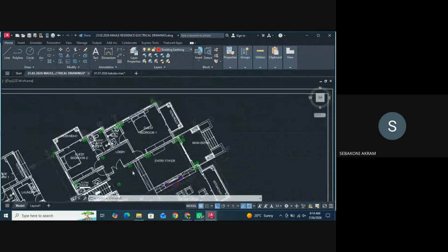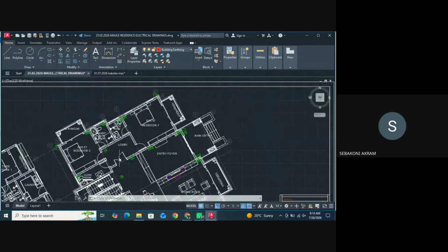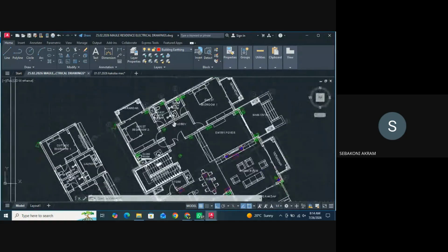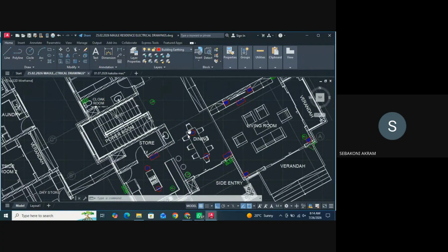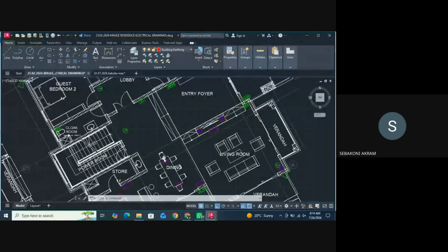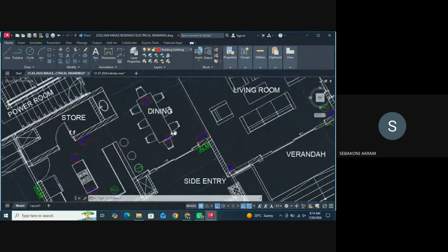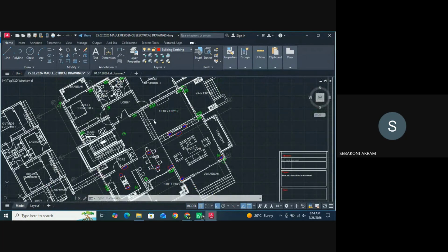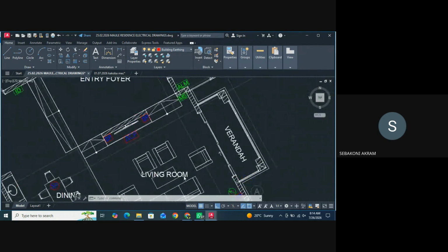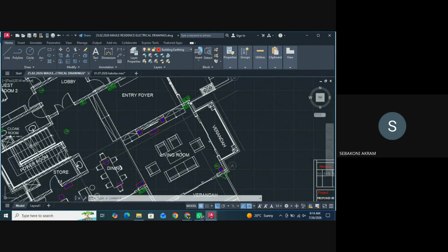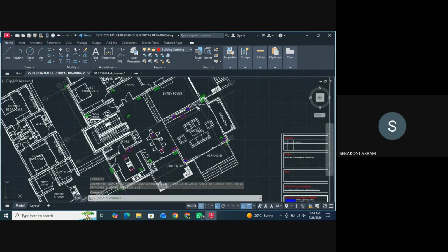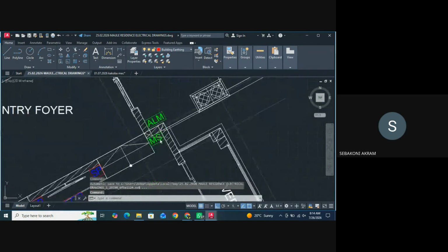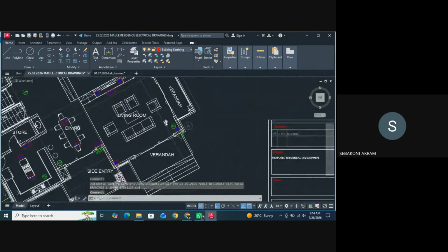I put a lot of cameras in this house, but it depends on the client, because you see which points are really critical to have a camera. So it will depend on the client and his technician, their pricing, and how they cut off some of the things. But for you, you follow your literature when you design, because motion sensors are put at points of entry. Like at that point, you put a motion sensor there at the corner, at the top.